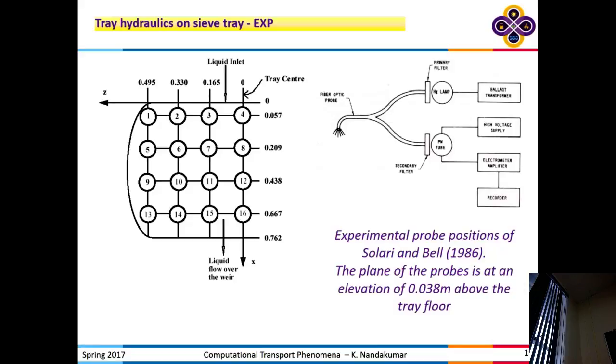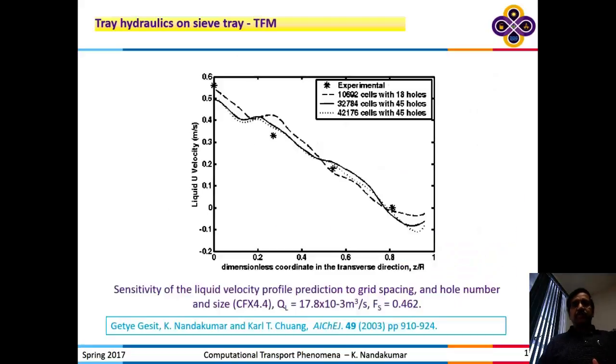So in this particular case, they gave us exactly 4 data points across the diameter. And so this is a quantitative comparison. The student went on to compare the velocity along the diameter of the tube. So the velocity was not plug flow. It was changing quite dramatically. And the three curves that you see are from the CFD simulation for a two-phase mixture.